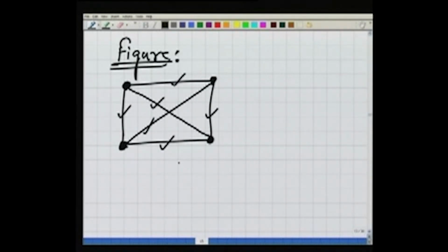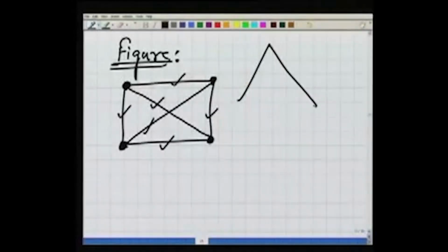Then also a corresponding figure, one more figure could be, and this is an important observation, as we discussed earlier, that triangulation by measuring the angles provides better geometric conditions for our checks, for adjusting the angles, which is not so in trilateration. In order to have the same kind of internal checks or geometric conditions in our observation, our figure will become more complex.